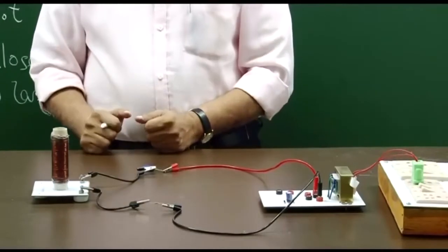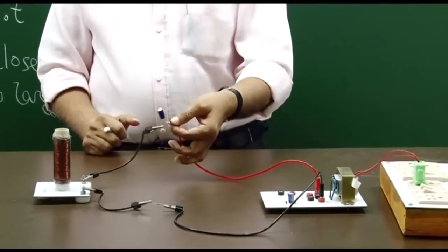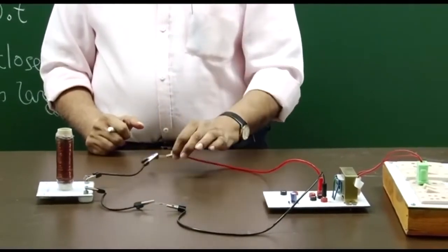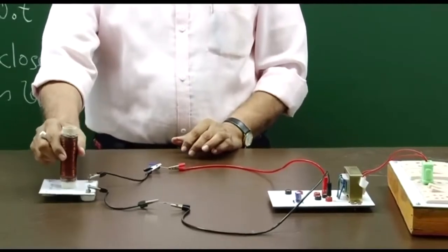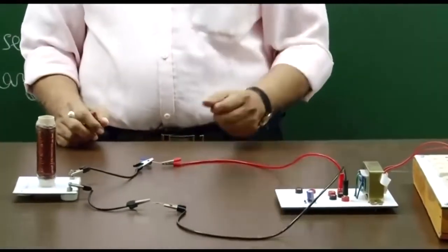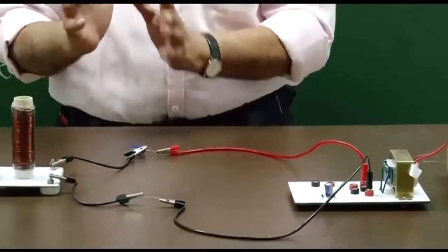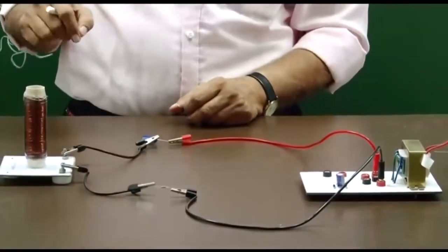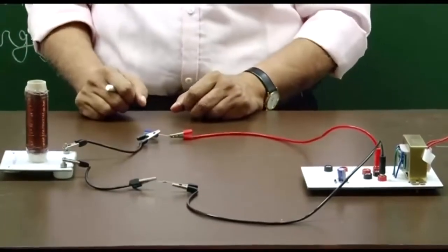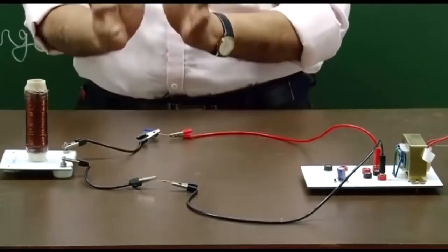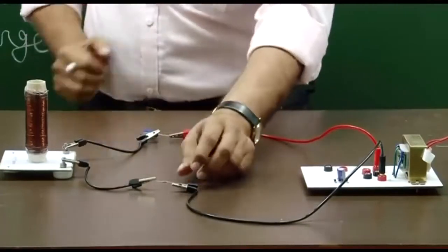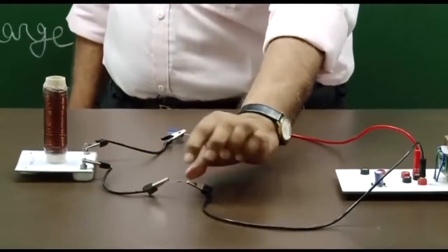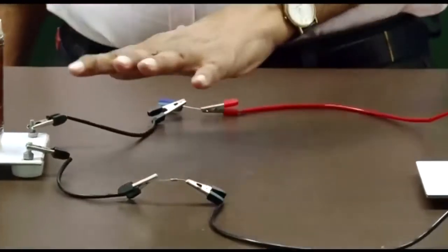And in that lecture I told you that if you have a capacitor and an inductor and you connect them, there is a natural frequency which is 1 by square root of L into C. Some damping is always there, some resistance is always there. So, in the circuit you have some resistance, and then